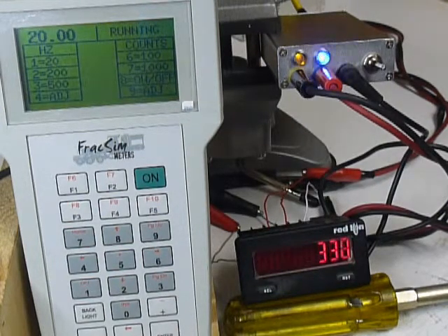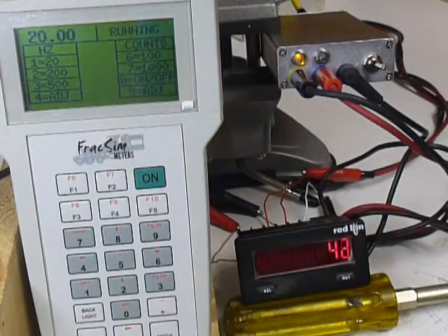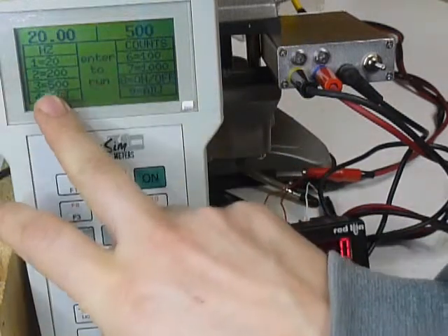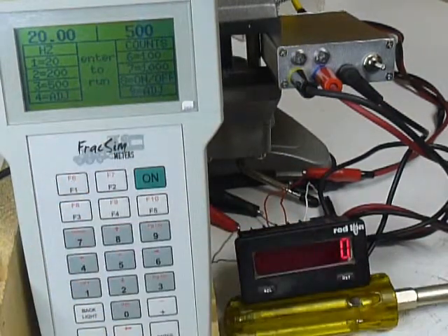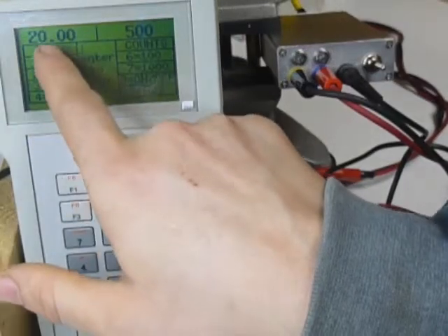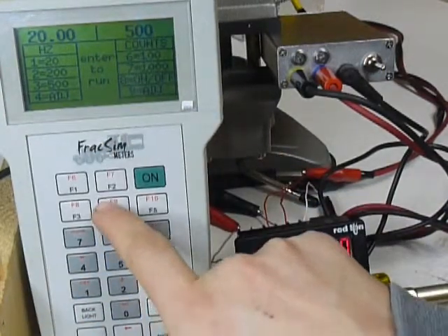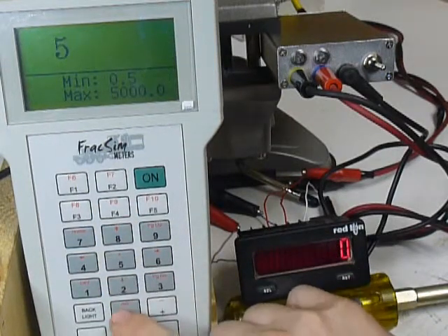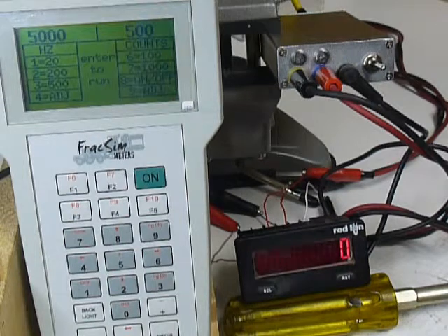Now this would be particularly handy if the encoder system, measuring system, was working, but you were not sure if it was working accurately. Then what you could do is put in a large number of pulses, and a high frequency like 5,000 Hertz, maybe you were worried that you're overspeeding the counter system. And to demonstrate that, if I wanted to increase the hertz, I could just go over here, press F4 for adjust, and put in something really fast, 5,000 hertz. So 5,000 hertz for 500. Let's see what it does now.